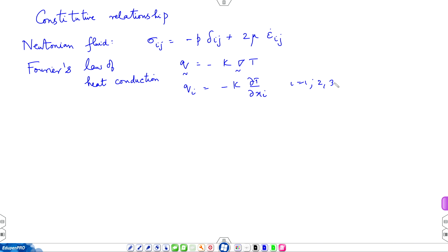So, if your fluid medium like blood is not Newtonian, we call it non-Newtonian. Similarly, materials in which q is equal to minus K gradient of T is not satisfied are called non-Fourier media. But for the commonly encountered materials, Fourier's law of heat conduction is known to prevail in the sense that thermal conductivity can be well defined.